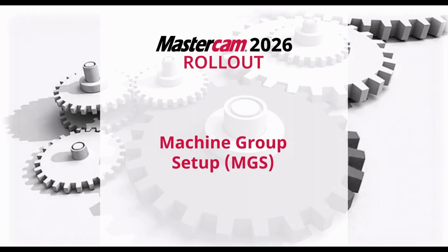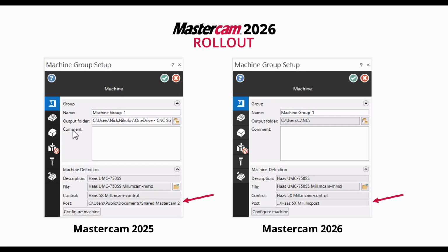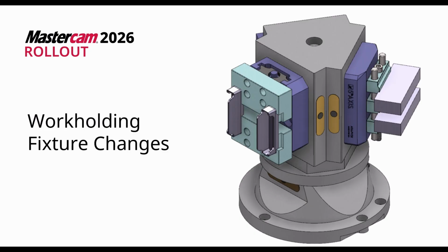Over the last few years, we have seen many enhancements to the mill machine group setup. In Mastercam 2026, we now get an enhanced display. You can see in 2025 we just saw Files, Tools, Settings, Stock Setup. In 26 we get to see and have direct access to every tab. They've also made enhancements to the way that long file paths are displayed to make it easier to see which files in use. They've also made some changes to the work holding.